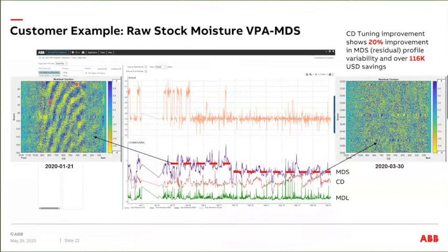See this kind of a spiral pattern. One of the things you'll say is, well, CD, you typically jump right on mapping. This one actually was over control. There was over control on a re-wet or air water spray, and that over control is actually causing the CD actuators to oscillate in the MD direction. I know there's a lot to digest, but basically if you have a mapping issue, you get what they call a barbershop pole or spiral pattern. You're also getting it here, but this is more from over control.